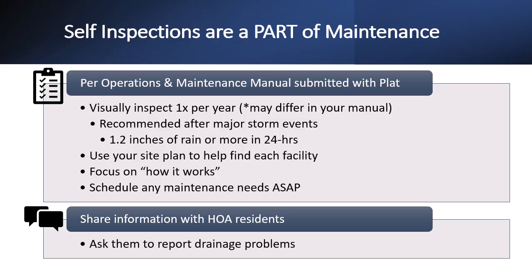Note that self-inspections are a part of maintenance, since you cannot address maintenance problems that you don't know exist. How often to inspect your stormwater facilities is outlined in your Operations and Maintenance Manual if your plat has one. Some plats may not have this. However, if you inspect once per year, you will be able to address any concerns in a timely manner.